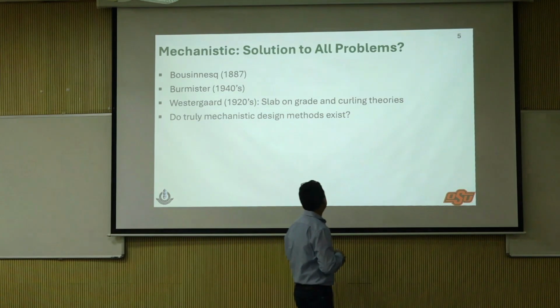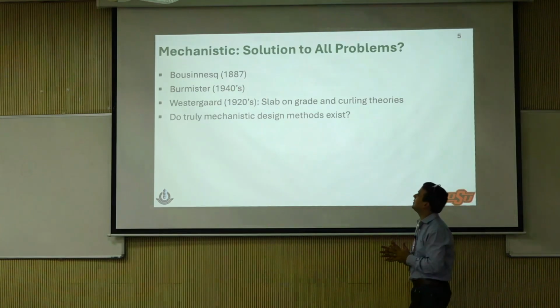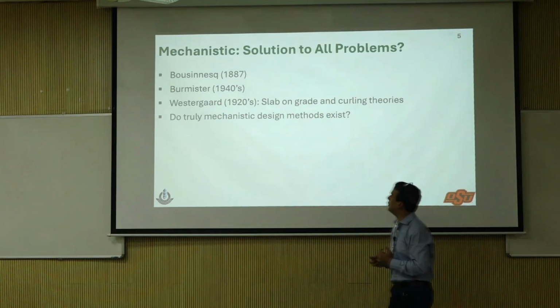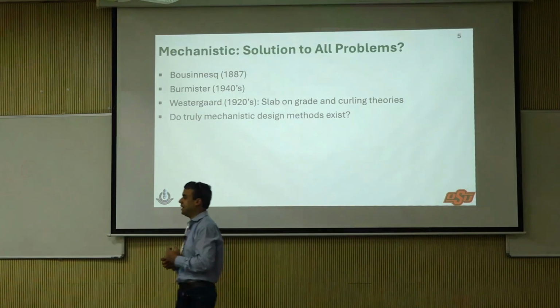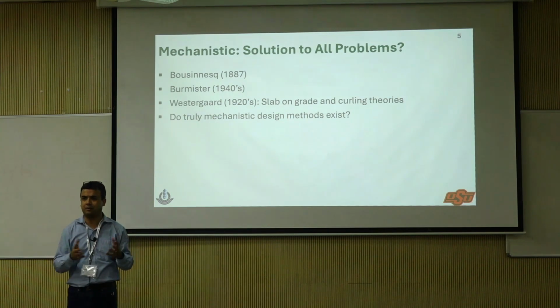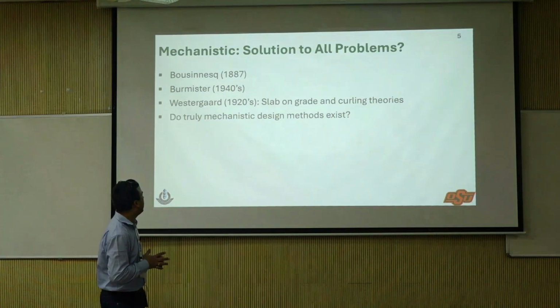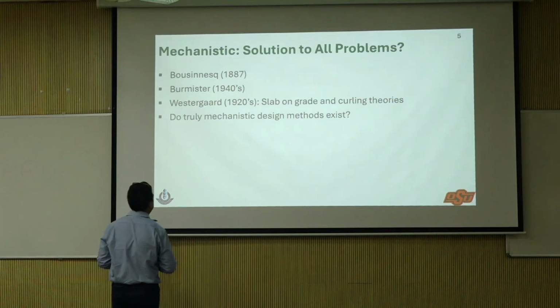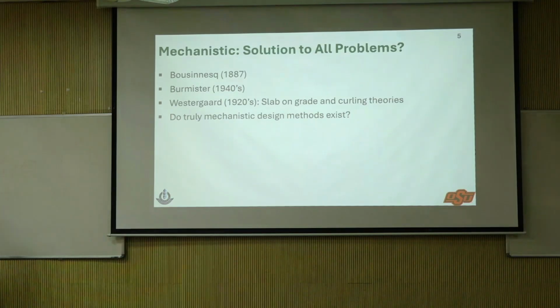So in India, there has been a lot of work as well, but it is all again layered elastic analysis, and then Westergaard on the concrete side, slab on grade and curling theories and stuff like that. The concept of dense liquid foundation, and I don't know if some of you know this or not, Winkler foundation and stuff. Do truly mechanistic design methods exist? Right. So based on that, again,